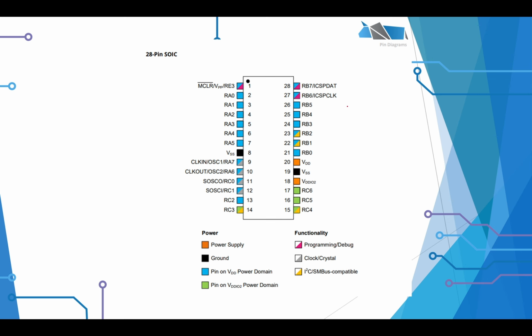I've got all the right connections. Trust me, I have all the right connections. We definitely have a master clear. We have a data line. We have a clock. We have a VDD and a VSS. Why? Because it programmed. We know those things. It has the program I wrote inside of that chip. You have to trust me. I'll get a kit for it and prove it. I don't have to. The issue is these new chips come with power domains.